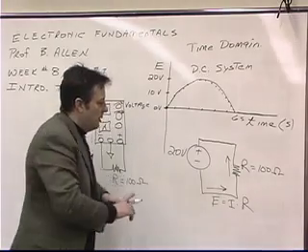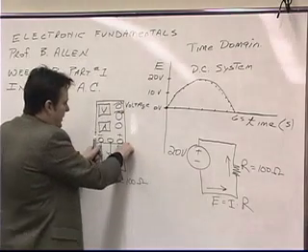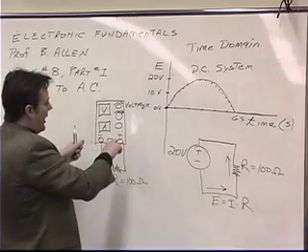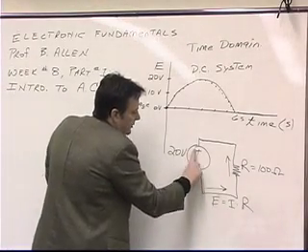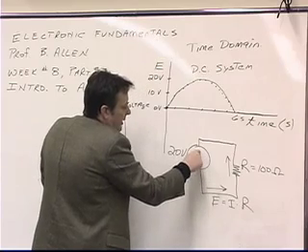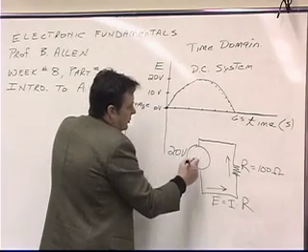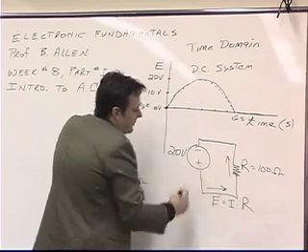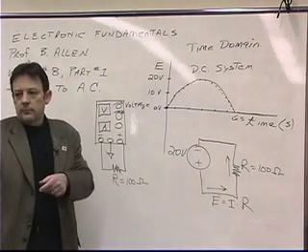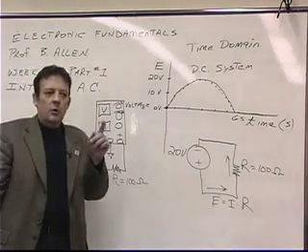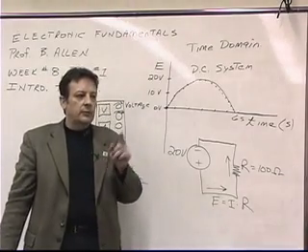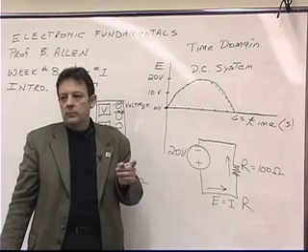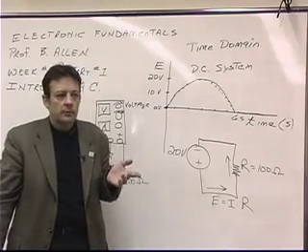It reverses, because what we've done by taking the leads and pulling them out and swapping them is we've taken these polarities and swapped them from positive negative to negative positive. And remember, with electron flow, the current always leaves what terminal of the battery? The negative terminal. Okay.